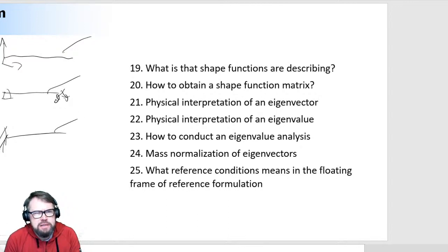But you have to understand that the eigenvalues and eigenvectors are linear dynamics, so they are linearized with respect to reference coordinate. Whereas in multibody system dynamics, we are describing the nonlinear dynamics. So that's why this is confusing. It doesn't really matter how you introduce the reference condition, but what matters only is how the deformation looks like.